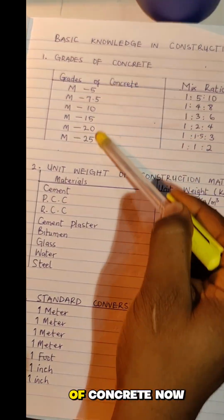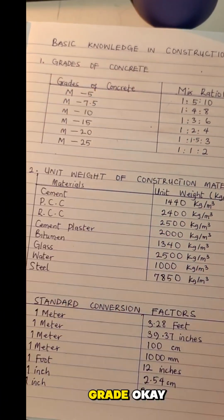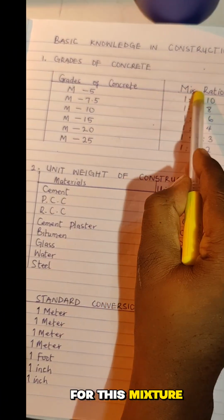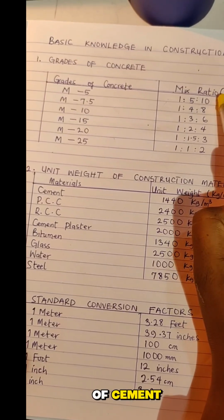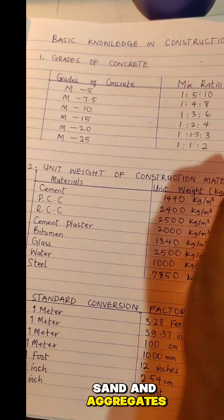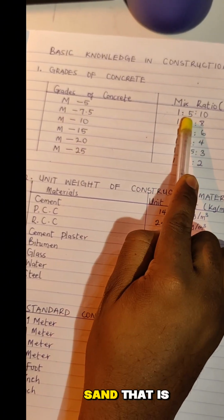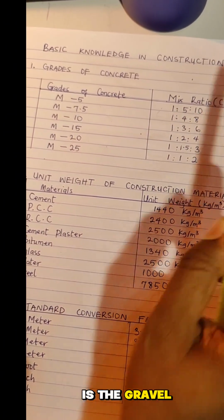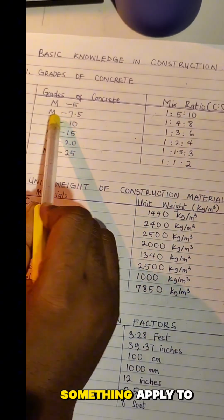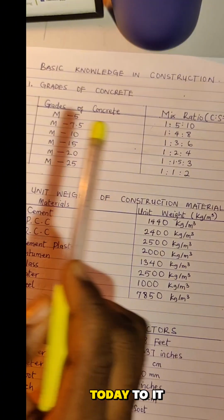So each grade of concrete now has its own mix ratio to achieve this grade. Okay, for this mix ratio, note this is the ratio of cement, sand, and aggregate. So your 1 is the cement, 5 is the sand, that is the fine aggregate, then 10 is your coarse aggregate, that is the gravel. Same thing applies to all the grades of concrete.